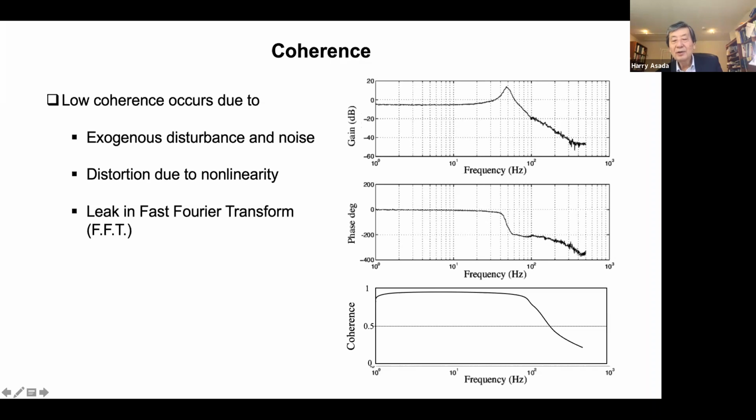So you're a little bit concerned about the fidelity of the estimation, right? If that's the case, I strongly recommend computing the coherence. The third plot is a coherence curve. As I said, higher is better. 1 is the best, and 0 is no confidence. So if you see this, it's high fidelity up to this point, and after that it is declining in some way. So something is going on.